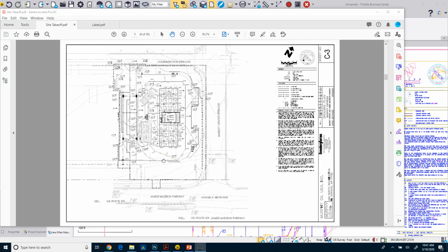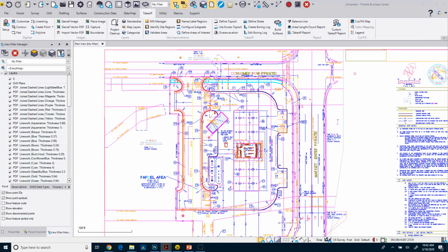All right, so now to start the 3D takeoff phase, we need to bring in the grading plan so that we can get our contours and elevations put into our project. So we've got the grading plan sheet. It's sheet number 6. In the previous chapter, 2D, we only worked with the site plan. So I'm going to show you how to match up this grading plan to our site plan.